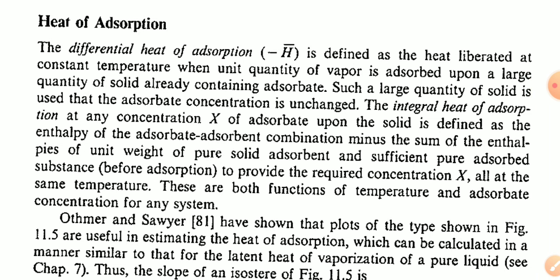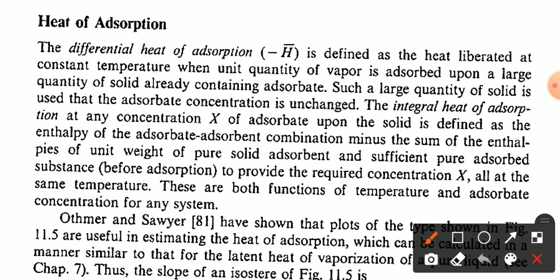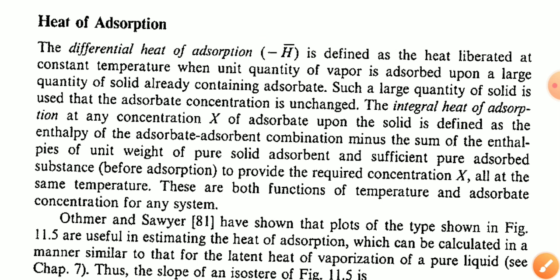Okay, let's start. The differential heat of adsorption, the enthalpy change, is defined as the heat liberated at a constant temperature when a unit quantity of vapor is adsorbed upon a large quantity of solid already containing adsorbate.